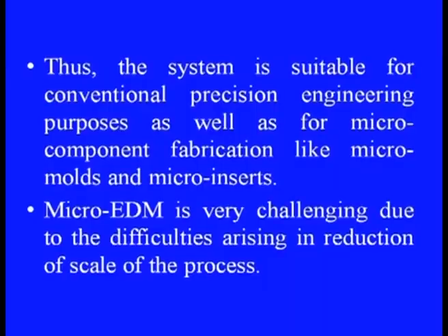Thus, the system is suitable for conventional precision engineering purposes as well as for micro component fabrication like micro molds and micro inserts. Micro EDM is very challenging due to the difficulties arising in reduction of scale of the process. Fabrication of small electrodes having small inter-electrode gap, achieving accuracy, removal of debris, keeping HAZ or heat affected zone to a minimum are very challenging issues in micro EDM.